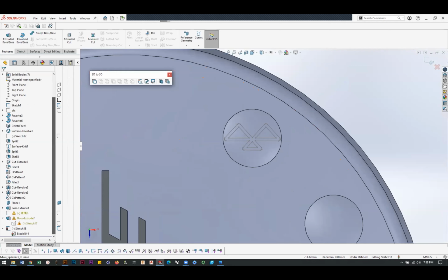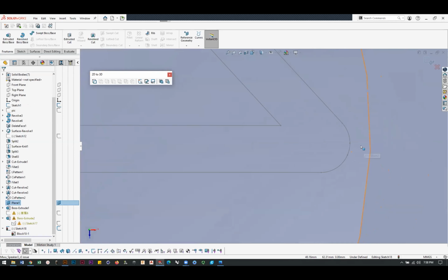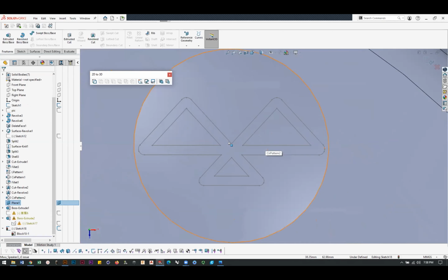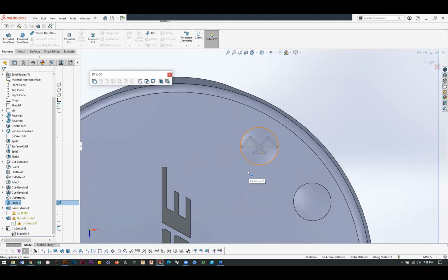Anyway, I'm on the right track with this piece at least. The block seems to be working. Guys, everybody get into the habit of really investigating, zooming in a lot. If you see strange points hanging out, or if your line work is segmented in odd ways and you feel like you could redraw it in SolidWorks more easily, like I just did, then that's a good way to handle it. Native line work will always work better than imported line work in CAD software.